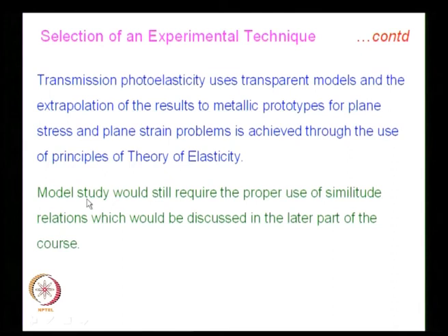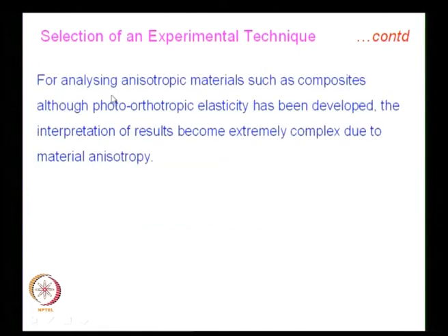You are actually using a model, and model study would still require the proper use of similitude relations, which would be discussed in the later part of the course. For analyzing anisotropic materials such as composites, although photoorthotropic elasticity has been developed, the interpretation of results becomes extremely complex due to material anisotropy.